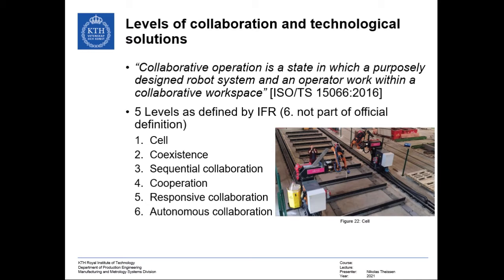Fences are used to prevent the entry of the robot's working space. And fences usually incorporate gates which are equipped with interlocks. These interlocks are designed so that all automatic operations by the robot and the associated machinery will stop when any gate is opened.